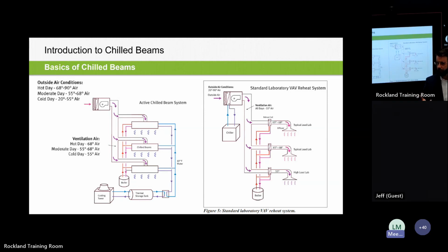That's becoming a common approach where you manifold and combine those together and you essentially just make sure that it's diluted enough. I know it comes down to the client requirements for contaminant concentrations or the dilution in the exhaust, but we've seen it where you're combining the general exhaust with the fume hood exhaust and doing research to make sure it's diluted enough, based on the types of specimens or items they're researching.